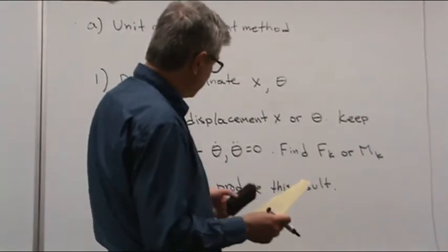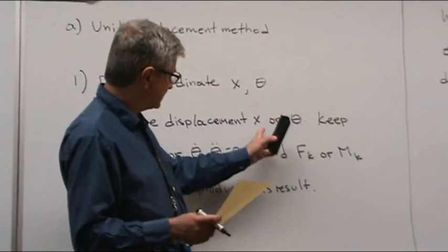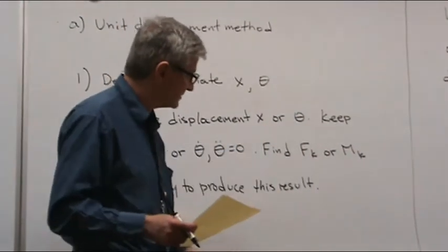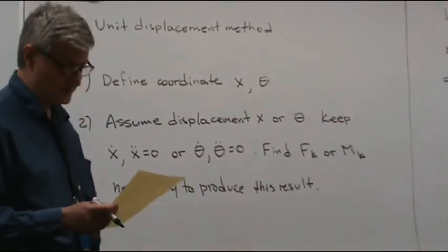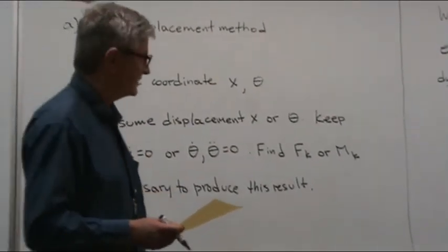Okay, so once you find this force, if you divide it by the displacement that corresponds to the force, that will give you the equivalent stiffness.